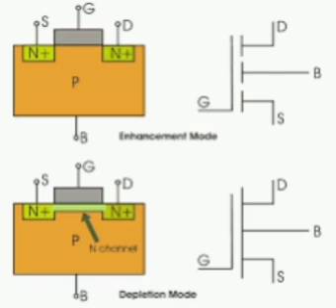FET as a voltage dependent resistor. JFET has a major application as a voltage dependent resistor. RDS equal to RDS on by 1 minus root over VGS by VP, where RDS on equal to channel resistance when full channel is available for conduction. A means half channel width. W means effective channel width.